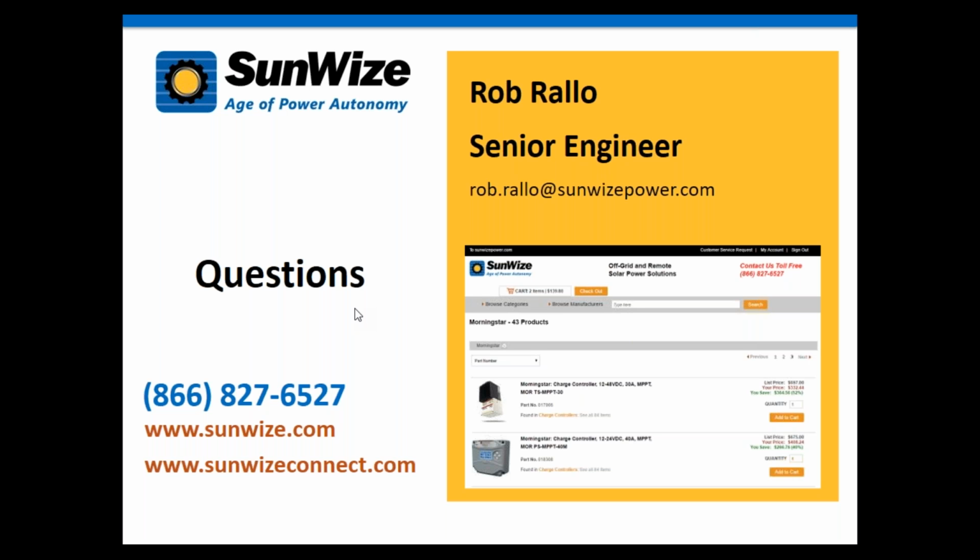I actually don't know myself. Actually, I do, because I did work for a module manufacturer at one point that I will not mention. But no, the way it's laminated with the EVA, which is basically a clear glue in there, you cannot remove the glass. That is not possible. Now, that being said, you can get to some of the ones on the back. So if the connection failure is on the front, no, you can't get to it. But if there's a connection on the back, yes, you can.